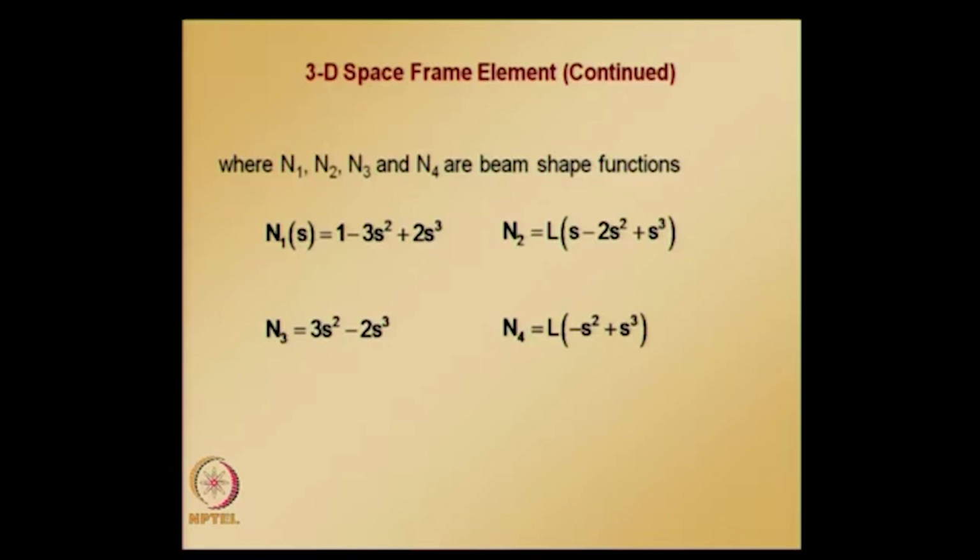And using an approach similar to what we did when deriving equations for the beam bending problem, it can be easily shown that the bending moment is given by this and the shear force is given by this. The only difference is that a negative sign is getting appended. Substituting shape functions into the beam bending potential energy functional, the following equations can be easily derived by applying the stationarity condition.